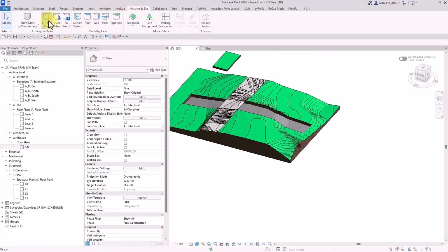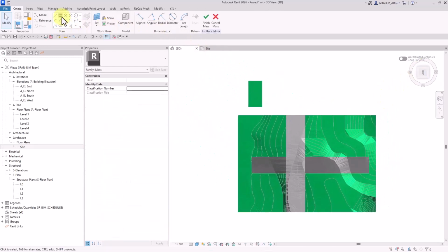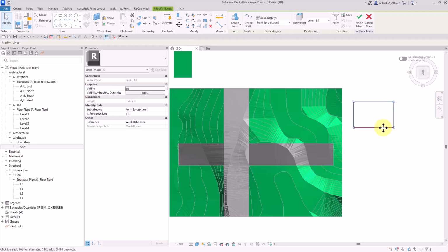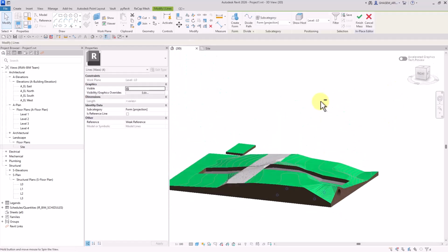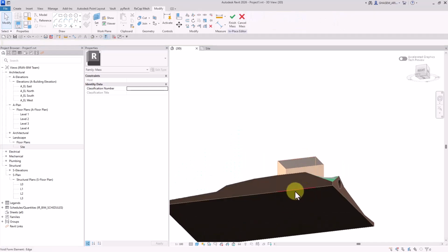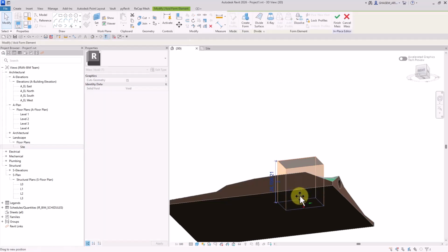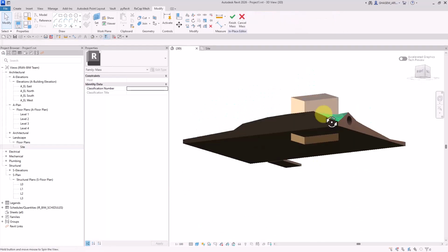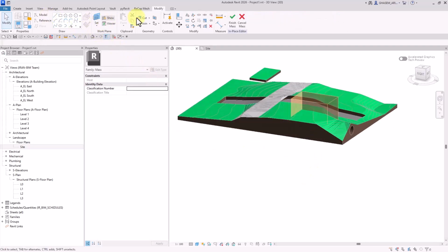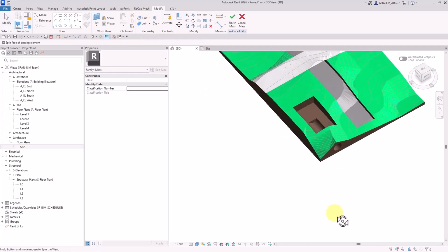To give you another example, from massing, inside, and place. Okay. Let's set a rectangle outside the topography. Then I'm going to move it here. After that, I'm going to use void to create a void here. Okay. Moving this a bit more downwards. Oh, no, actually, let's move it upwards instead. And now let's create the cut. Again, as you can see, we're going to get the cut.